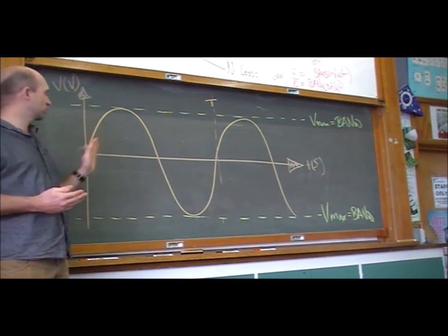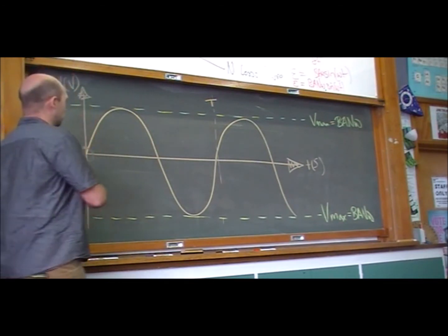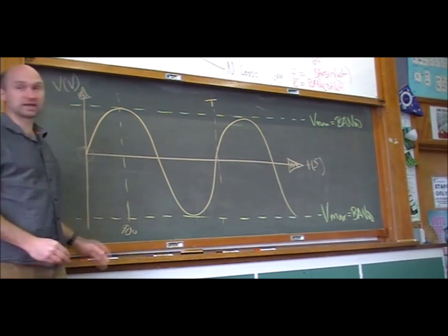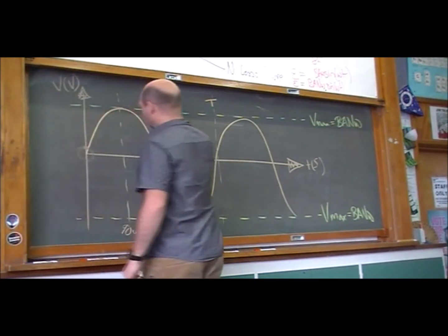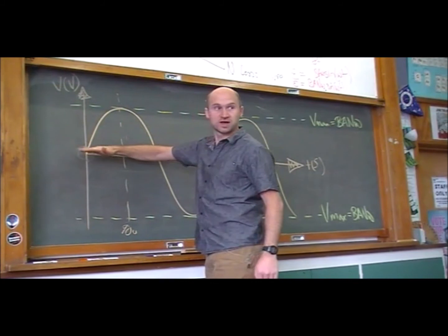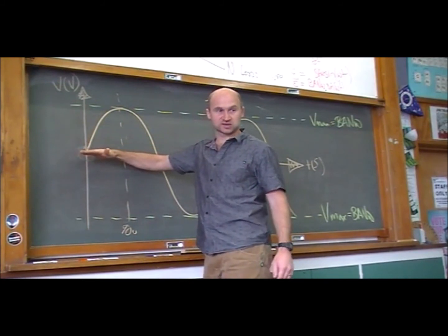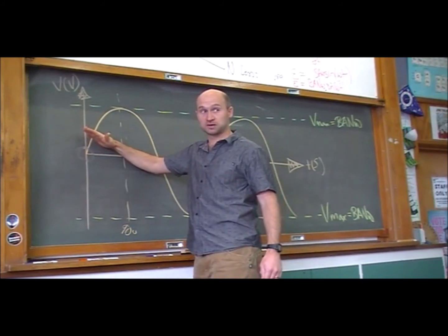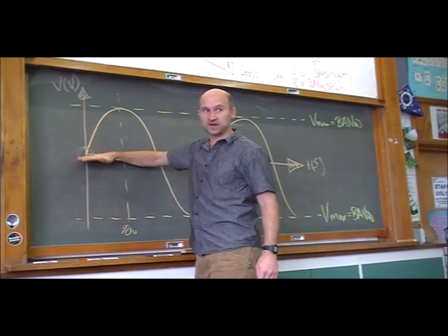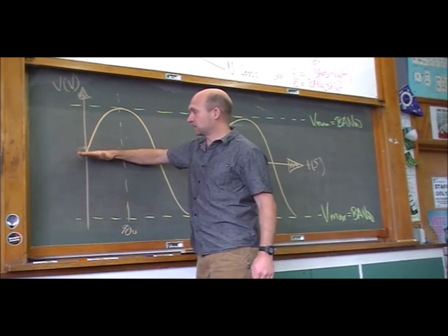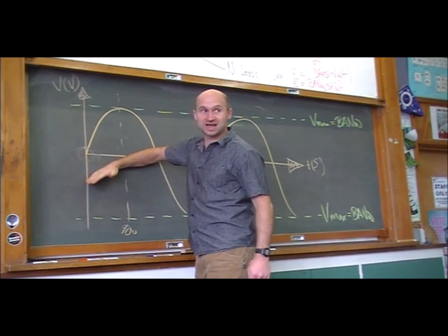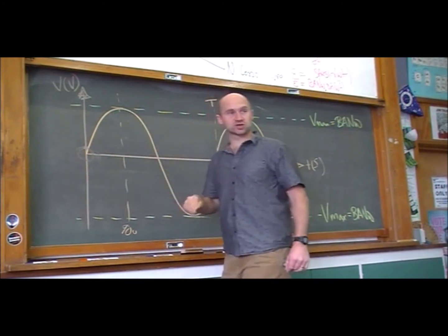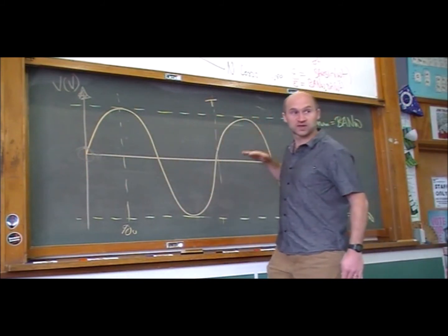when the coil is vertical. But then as we turn the coil through the first 90 degrees until the coil is now horizontal, at that point when the coil is turned around to be horizontal, it's got zero magnetic flux through it, but just a moment before it had some. And to go from some to zero, that's a really big change. And then to go from zero back to negative some, that's also a really big change. So we get a really big induced voltage at the point where the coil is parallel to the field.